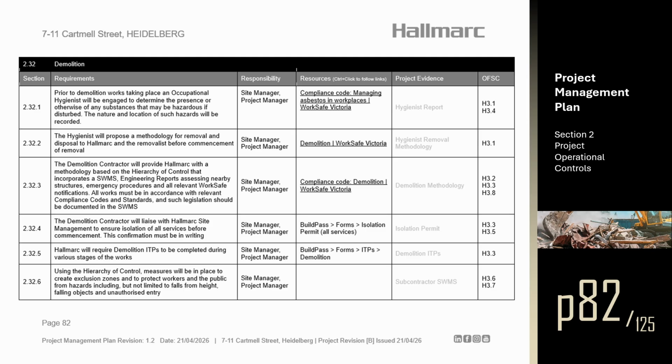All works must be in accordance with relevant compliance codes and standards, and such legislation should be documented in the SWIMS. Section 2.32.4. The demolition contractor will liaise with Hallmarc site management to ensure isolation of all services before commencement. This confirmation must be in writing. Section 2.32.5. Hallmarc will require demolition ITPs to be completed during various stages of the works.